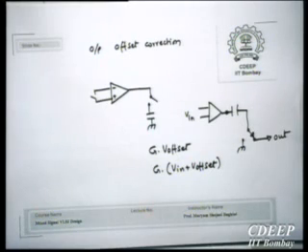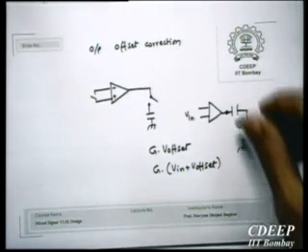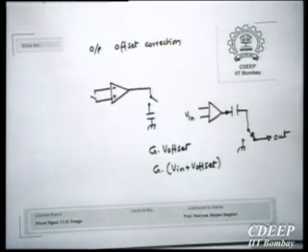In fact, in A to D conversion, very often we are talking of quasi DC. Okay, of course, time of conversion is important. So this capacitor should charge up to this difference within the time that you have given in case of A to D conversion. Okay, now we have two ways of correcting this offset. One is at the input, which you saw before. The other is at the output. Now, what are the pros and cons of using both of these? Okay, and then we will choose one of these.